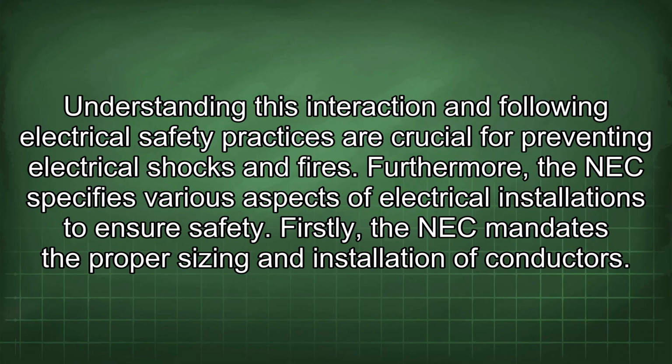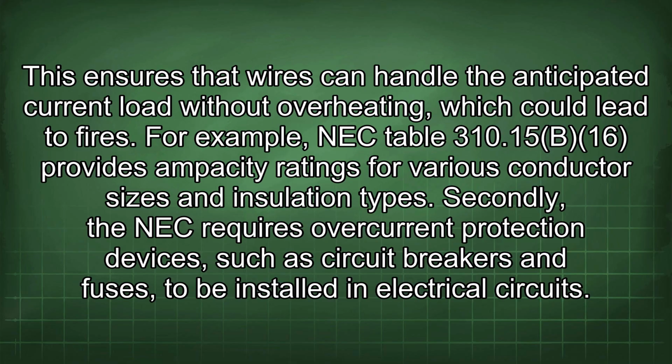Furthermore, the NEC specifies various aspects of electrical installations to ensure safety. Firstly, the NEC mandates the proper sizing and installation of conductors. This ensures that wires can handle the anticipated current load without overheating, which could lead to fires. For example, NEC Table 310.15(B)(16) provides ampacity ratings for various conductor sizes and insulation types.